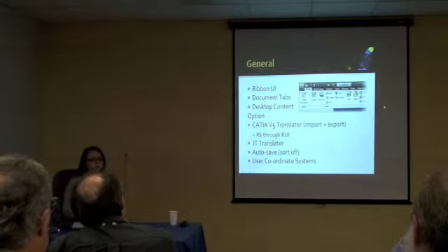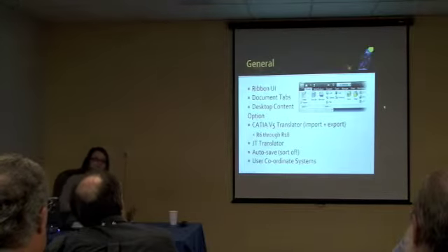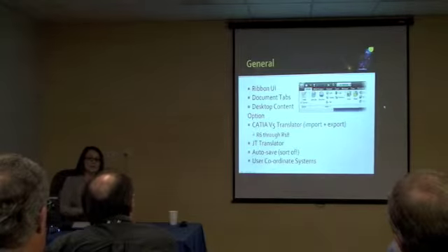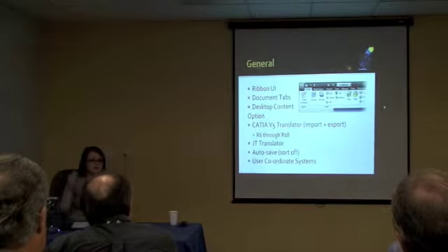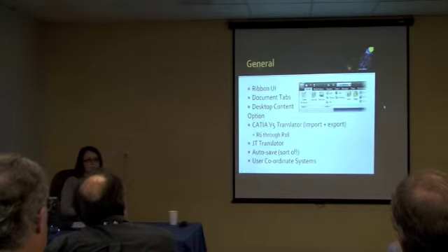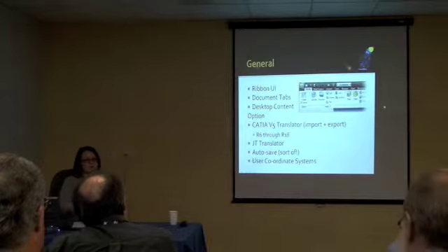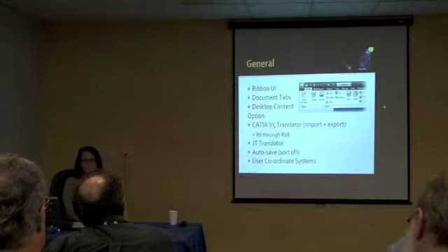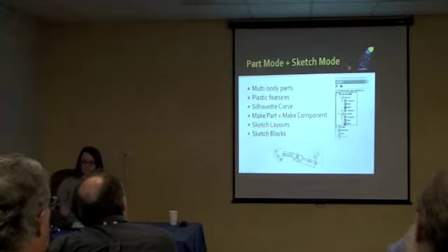And user-defined user coordinate systems. Now, I'm sure most of you already know that I haven't come from an AutoCAD background, I came from a multimedia and 3D Max background, so the user coordinate system concept to me is a new one and I'm not the best person on it at the moment. What it basically means to me from what I've seen of it, is that you can initiate your own user coordinate system to place work planes or sketches on a different set of planes. It's there to allow you to redefine your sketches to a different position in your model. Sort of like a quick way of not just creating 3 work planes, but 3 axes and a point at a different position. So hopefully you guys can integrate that if you see it useful.